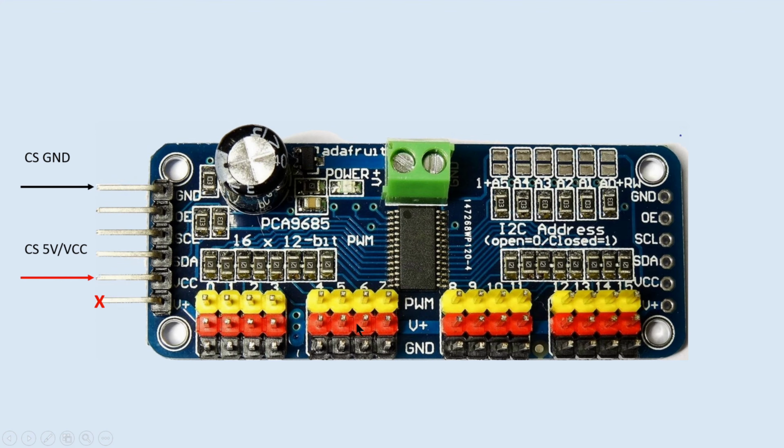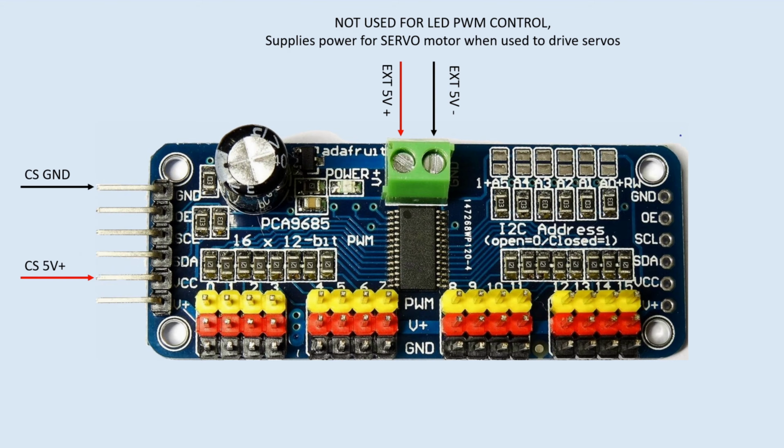And that powers the red pins in the middle, which is what powers the motor on the servo. Because the servos draw too much current, we wouldn't want to use the Arduino for that, so we put an external power supply for that. And that's what this shows. We will have a servo connected at one point, and so that's where the power would come in from.